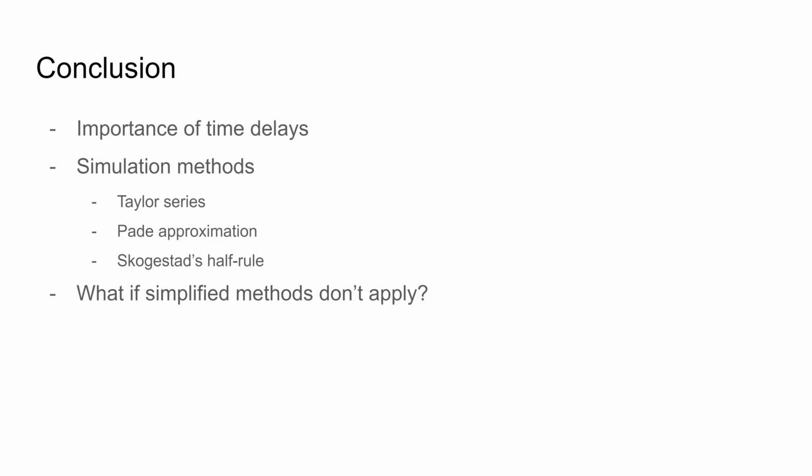So in conclusion, in many real-world processes, time delays are a very important consideration. They occur almost wherever material or energy are being moved. They can have a significant impact on the process dynamics. Therefore, it is important to be able to predict and understand the process response to time delays. Several simplified first-order plus time delay methods were introduced, such as the Taylor series, Padé approximation, and the half rule approximation. And as we saw in a little case study, their accuracy was compared, and most of them do a great job of approximating much more complicated functions.